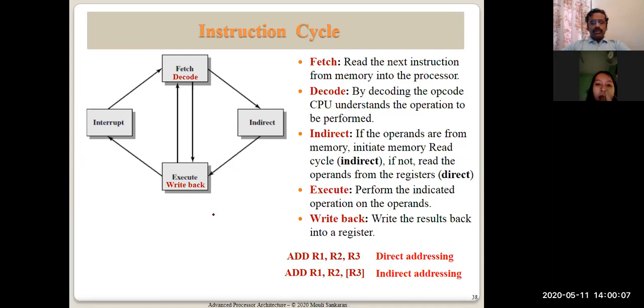The CPU structure what we saw here does everything within the CPU one after the other in every cycle. That means one instruction is fetched and it goes through all the steps before fetching the next instruction. That's why we call this CPU an unpipelined or non-pipelined processor.